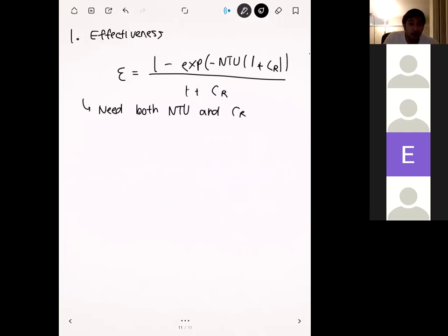All right. And so to do that, we first need our fluid properties. And so thankfully, both the fluids here are water. And so we can just evaluate the properties of water. In particular, since our water here is starting at 2 different temperatures, let's evaluate the water properties at kind of right in between. So it's going to be at 35 degrees C.